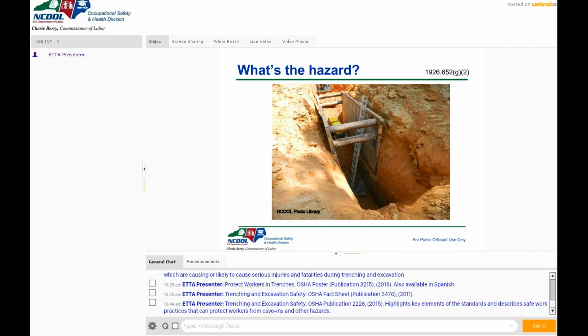What's one more issue that a lot of people miss here? Well, yeah, you got a piece of equipment down there, but nobody's running it right now. But we will be asking questions about that. There's something that a lot of people look at and don't realize more than anything else. Ladder, yeah. Well, the ladder's important. And remember, anytime you're using a ladder, it's got to be 3 feet or more above the place where you're exiting, unless it's secured.